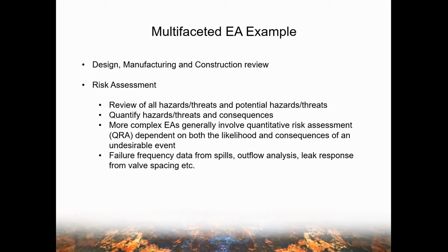For more complex EAs, I am highly suggesting that a quantitative risk assessment is important because it is important to look at both the likelihood and consequences of an undesirable event. I'm also suggesting that some of these risk assessments would involve failure frequency data from spills, doing outflow analysis, and looking at leak response from your valve spacing.